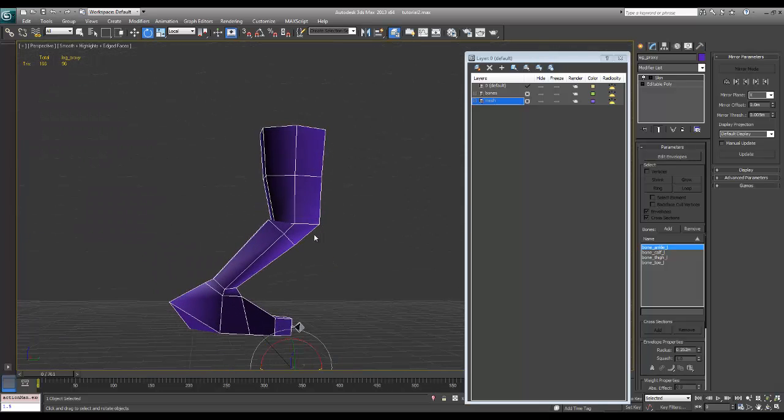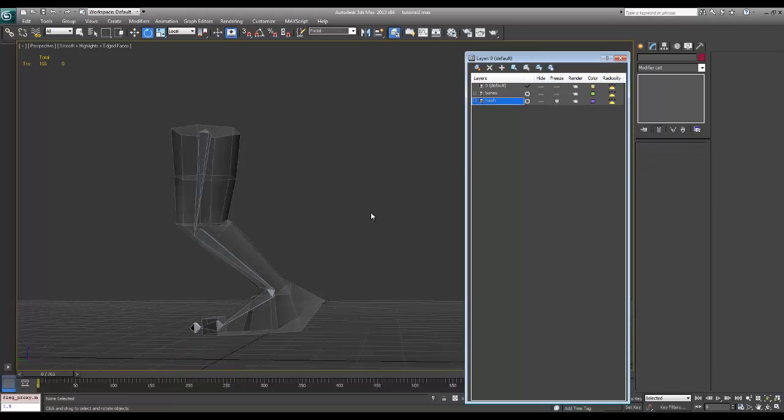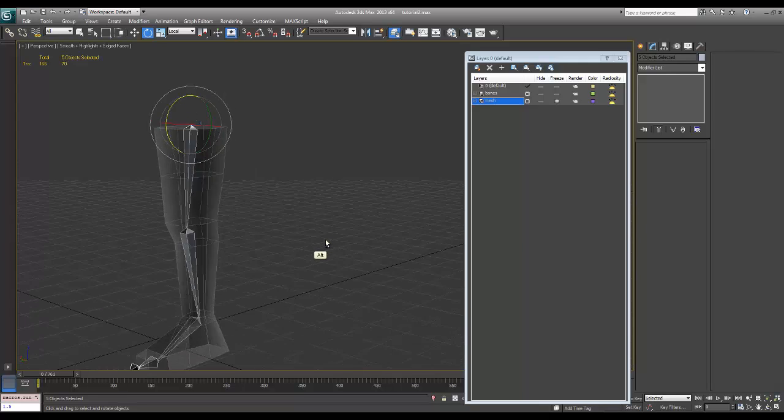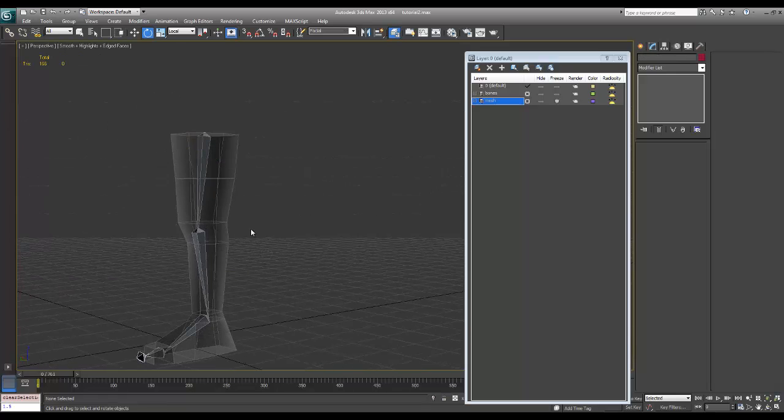Probably have some verts pull with the knee and the lower leg a little bit more. And obviously there's some problems here with the heel. So let's go to Alt-X again. Let's freeze our mesh. Double click on the top of the bone hierarchy, and remember Alt, right click, transform to 0, and we've reset our bone's rotation back to the 0 position. So now we can start adjusting our skin weights. Unfreeze your mesh, and now let's freeze the bones.